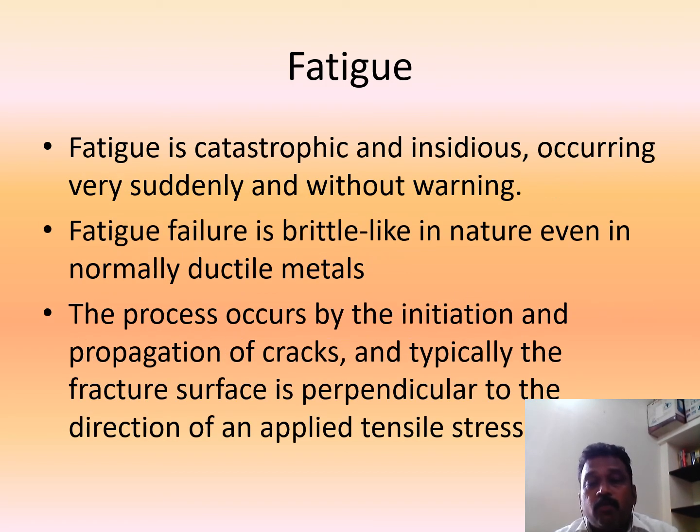Fatigue is catastrophic and insidious, occurring very suddenly and without warning. It will not give any warning, that is, it will not show any signs of failure. So it is brittle-like in nature, even in normally ductile metals. In the previous slides, we saw the cup and cone fracture. But when it is fatigue, when you are applying load repeatedly for a continuous duration, it will not behave like a ductile material. It will show failure similar to brittle materials due to the continuous application of load.